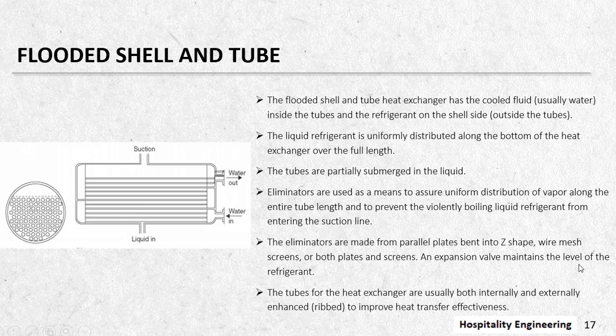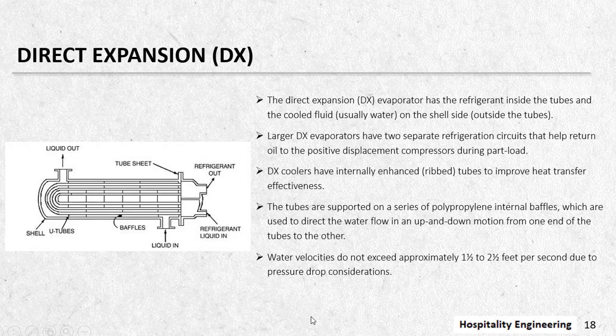An expansion valve maintains the level of the refrigerant. The tubes of the heat exchangers are usually both internally and externally enhanced to improve the heat transfer effectiveness.